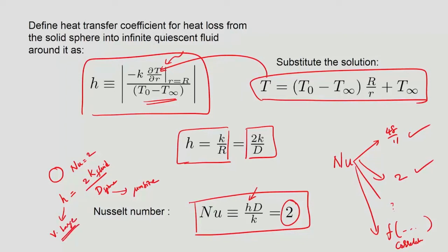So, when you want to solidify liquid metal without any partitioning, if you can spray this liquid metal as tiny droplets, then each droplet would have such a high heat transfer coefficient that it would freeze at almost a million Kelvin per second, and then you will have partitionless solidification. You get metallic powder that is very homogeneous.